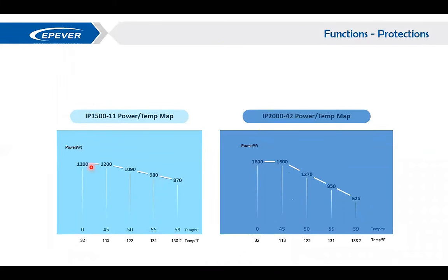The heat needs to stay below a certain level at which materials in the inverter will start to degrade. So what we call the protection against over temperature is, if you have an increased temperature from a certain point on, the inverter will try to derate the output power so that it will not be damaged by overheating. And at a certain temperature, it will completely shut down, and it will wait until the temperature comes back to a certain value. So this is the function that we call the temperature rating in inverter.